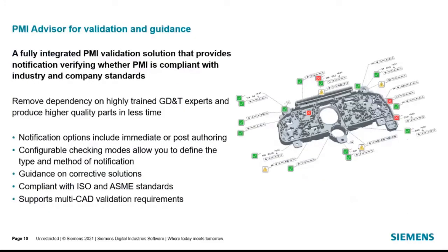I mentioned that the NX model-based definition solution also includes a PMI Advisor. The PMI Advisor provides validation and notification for immediate verification that PMI is compliant with industry and company standards. The solution provides a number of unique capabilities, including multiple checking modes, allowing you to control the amount of feedback you receive. For non-GD&T experts out there, the solution will advise on corrective solutions, making it easier for you to complete the task.